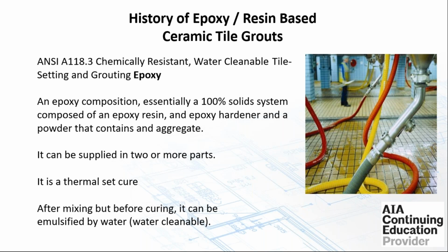There are a lot of differences with these grouts. When I first started in the industry and we were working with epoxy grouts, they were really difficult to work with. In most cases, you needed to use hot water to get them clean. A lot of times we would pre-seal the tile so that the epoxy would come off much easier. I also had to be careful where I dumped the residue.